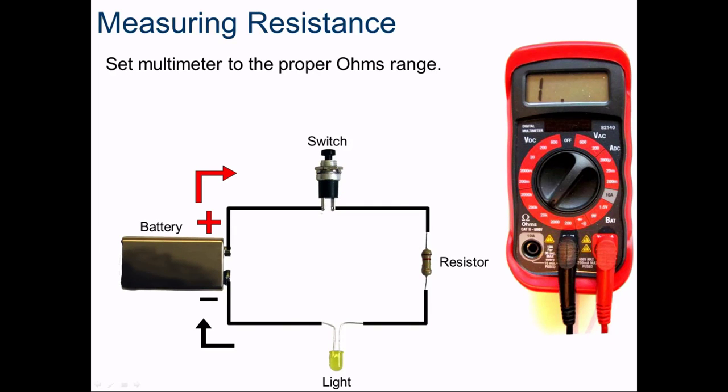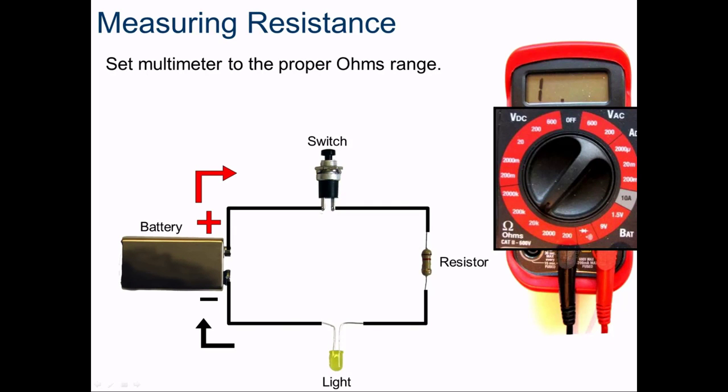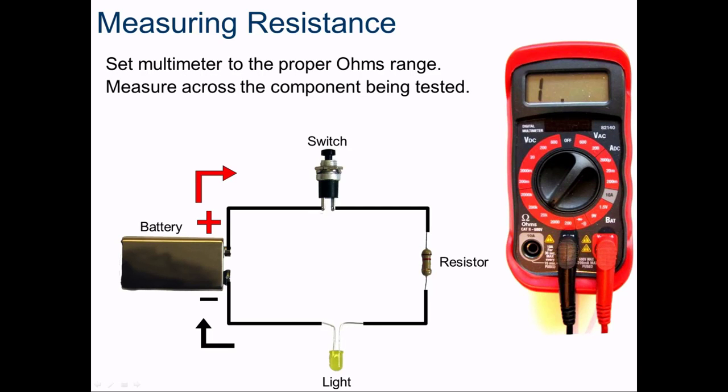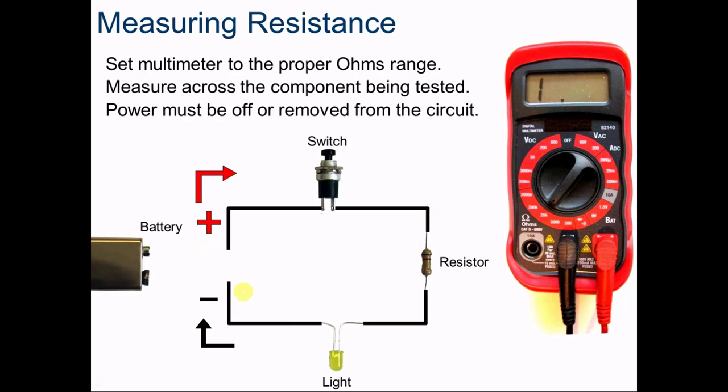Resistance, we'll set it to the appropriate range. Measure across the component, but power is off. Notice, power is off, and then we will measure across.